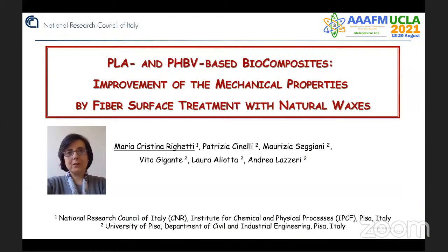In this contribution, I will present some results on green composites made of polylactic acid and ecopolymer polyhydroxybutyrate-co-hydroxyvalerate and natural fibers from organic waste, with the addition of natural waxes to improve the adhesion between the polymer and the fibers.